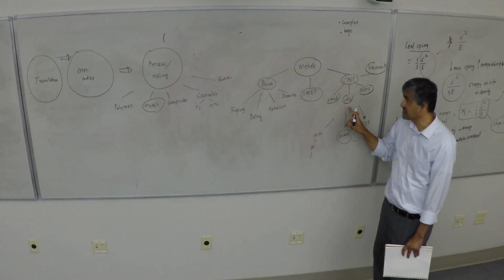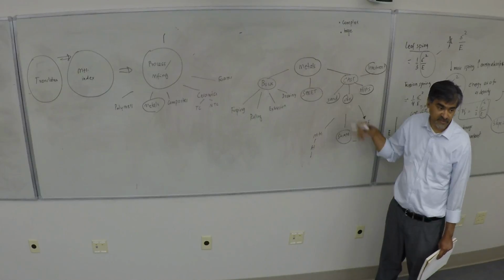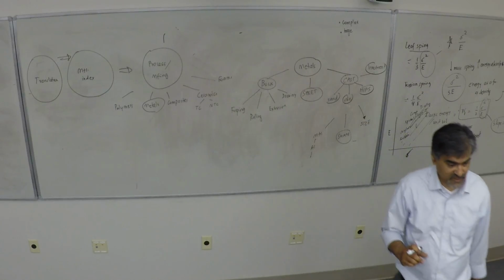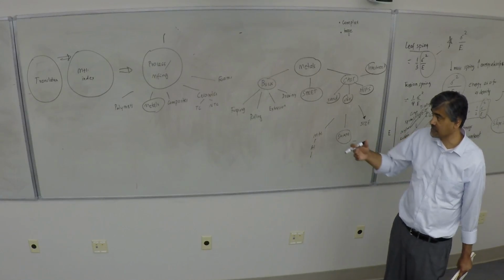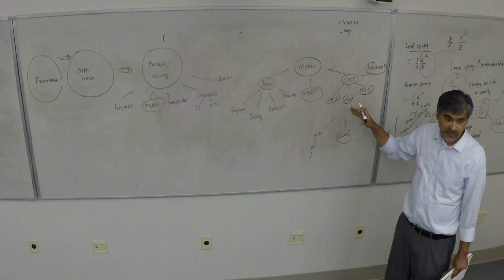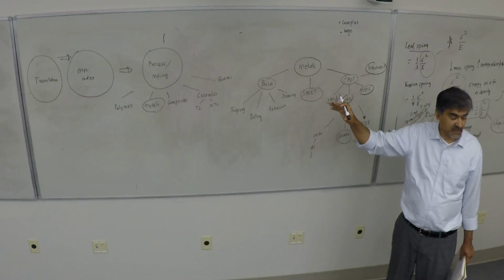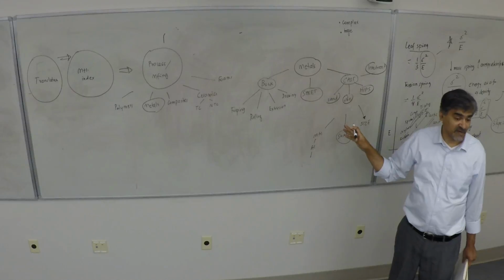If you are very high precision within the cast family, you probably want to look at die casting, which then gives you a lot of control on the casting. You can get very good wall thicknesses and things like that. So I guess the point I'm trying to drive across is, now as we go down to the processing side, we have to not only know, we did this material index selection and all that, whether the part is processable within the economical scale required for that.